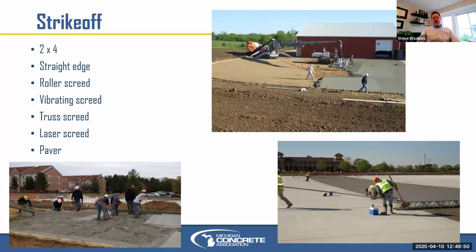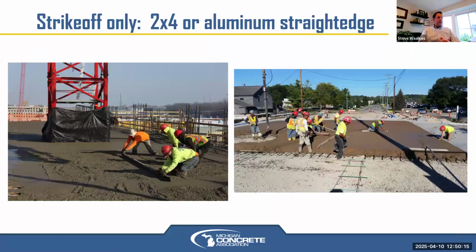A lot of times they'll pound grade stakes into the placement area so that they know the top of the stake is right at the level of the concrete, so they get the thickness and smoothness they want at the right elevation. But the laser screed pictured top right is used for a lot of parking lots, and warehouse floors are done that way. And then slip form paver as well. We'll have some shots of that as well.